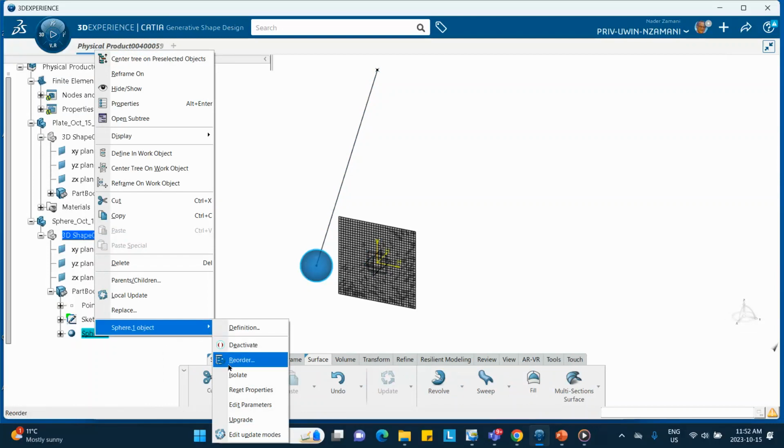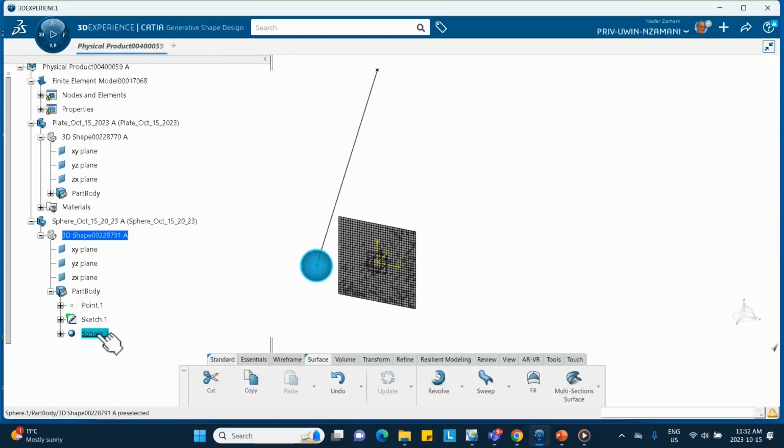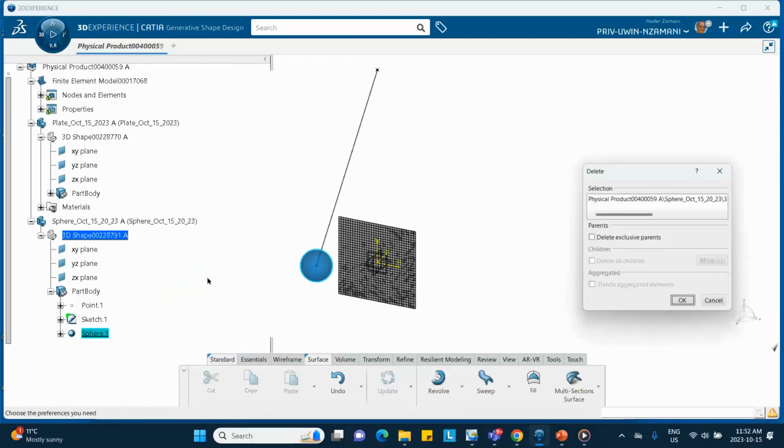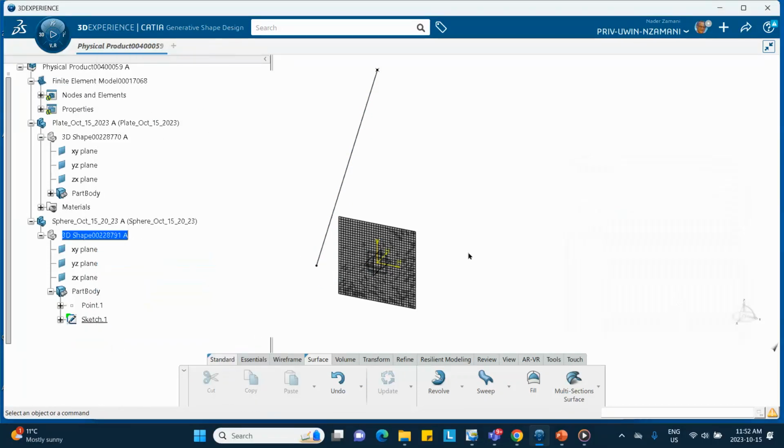But you know what? I'm going to delete it. So what I have to do is draw half a circle and revolve it about 360 degrees. Because I have all the machinery needed, I'm going to do it like this. I go to the sketch, the one that I drew this line in, and double click on it.